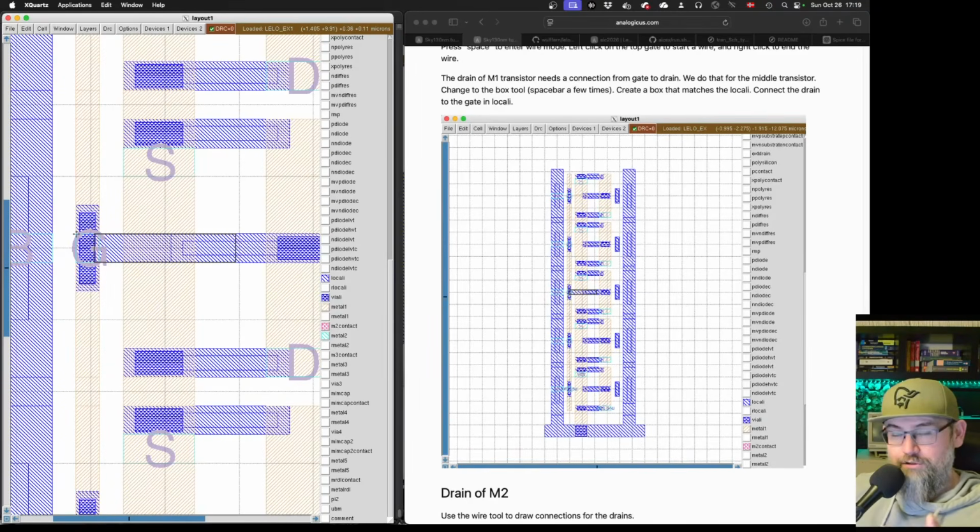In that type of structure, you can actually have dangling bonds. That means you have missing connections to other parts of the oxide. In those boundaries, or in those missing connections, it's kind of like you have what's called a dangling bond. It is a possible state for an electron to jump into.